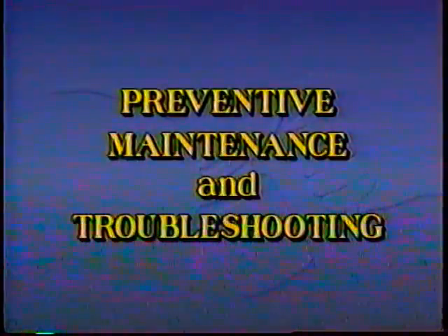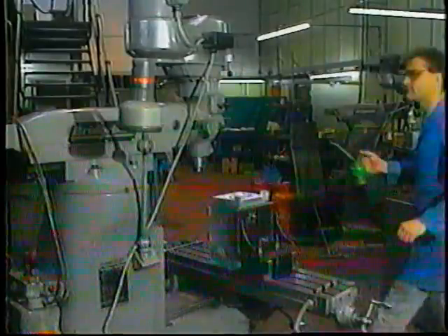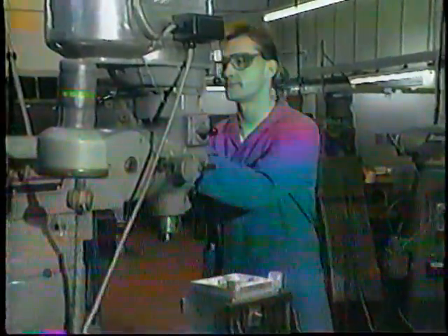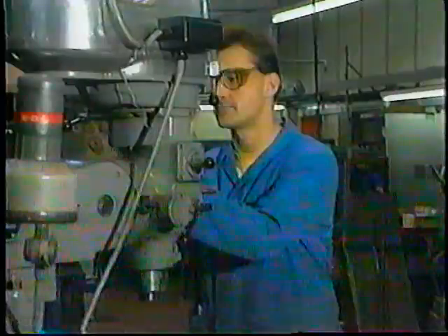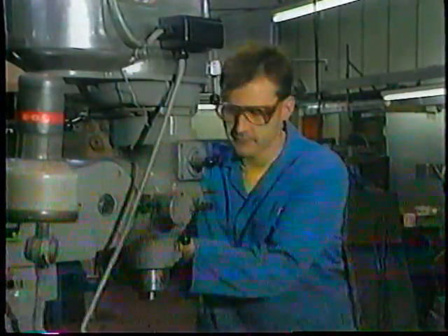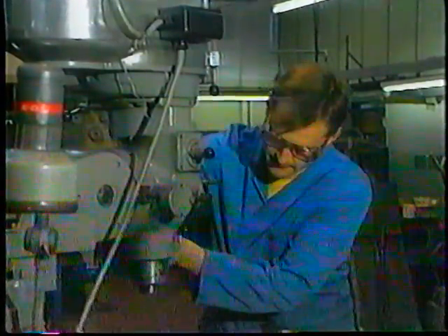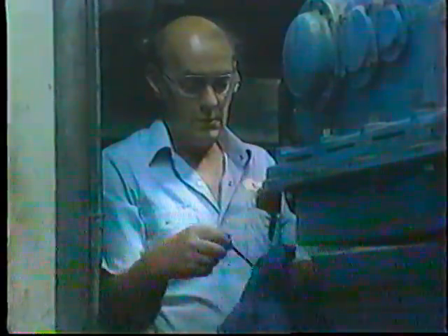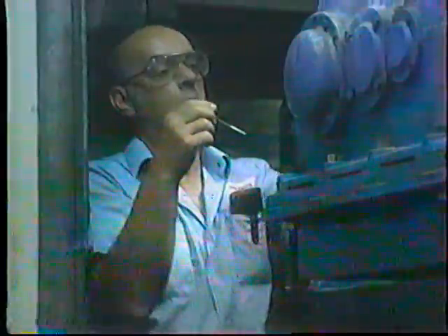Finally, preventive maintenance and troubleshooting. Another important part of your work is spotting potential problems with the machinery you are lubricating. In some preventive maintenance programs, routine inspections may be an official part of your job. You may be in the best position of anyone to notice bearings or gears that grind, whine, thump, or knock, and machinery that is vibrating, rubbing, or out of alignment or adjustment.